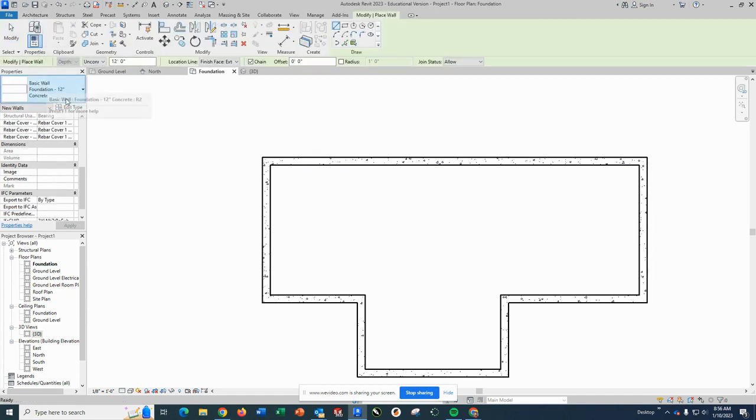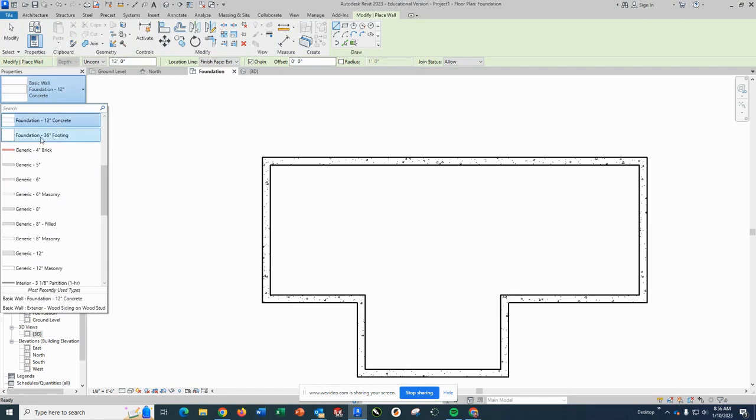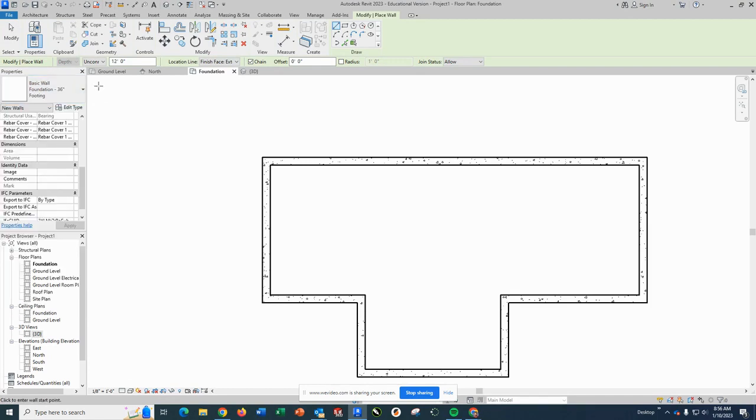I won't see the actual exterior wall anymore, which makes this next step a lot easier. I'm going to pick my wall tool. I'm going to switch to the footing. Okay, I am going to make it 1 foot tall. Sorry, I accidentally typed 0.1 foot tall. I'm going to use wall center line, because what I want is the center line of my footing to line up with the center line of these. So you go to these endpoints that have the wall center lines.